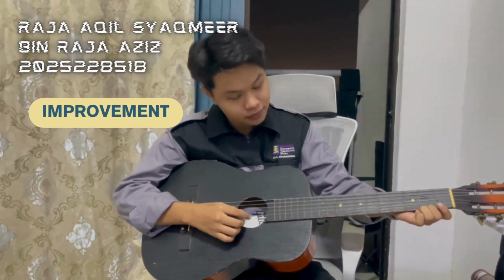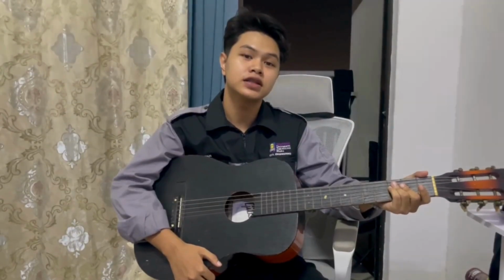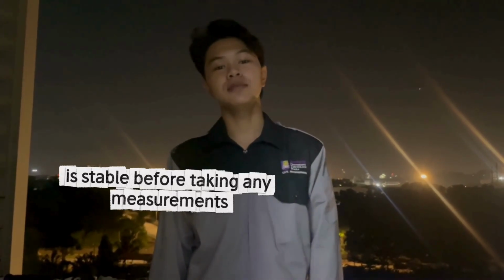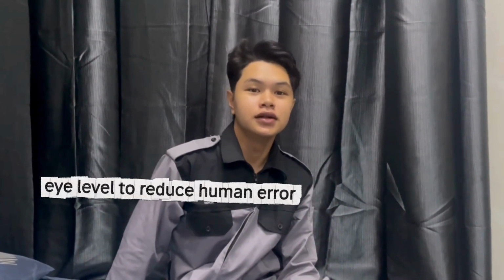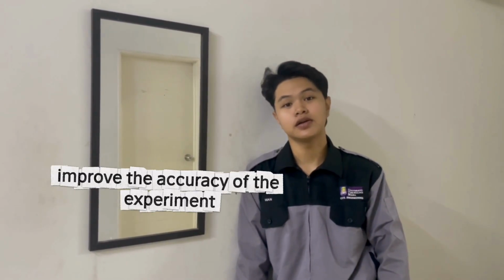So, Akil, what improvements can we make to get more accurate results? Okay, there are several improvements that can be made. First, we make sure the water channel is level and stable before starting the experiment. Then we need to wait until the water is stable before taking any measurements. We should also read the measuring scale at eye level to reduce human error. Last but not least, repeating the experiment several times and using the average value can improve the accuracy of the experiment.